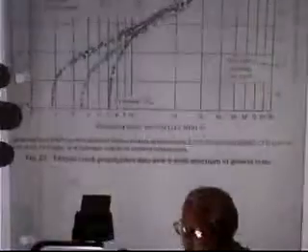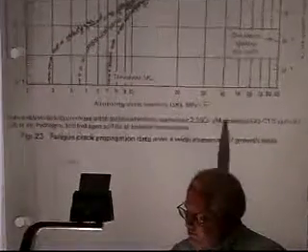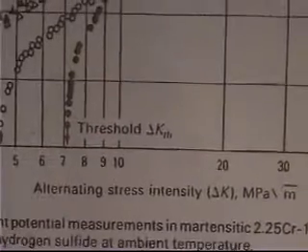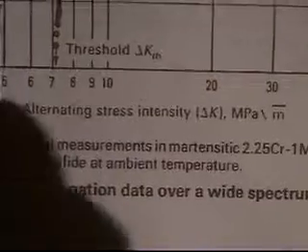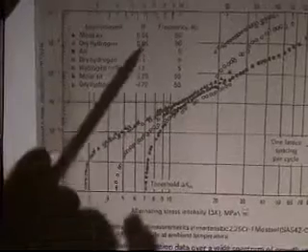You still have environmental effects. So this happens to be another pressure vessel steel. It's a chrome moly steel. It's a high temperature pressure vessel, so a boiler type of pressure vessel. And they measured it in moist air, dry hydrogen air, hydrogen sulfide, and frequency from 5 to 50 hertz. And R values is a stress value. We don't have to go through that.